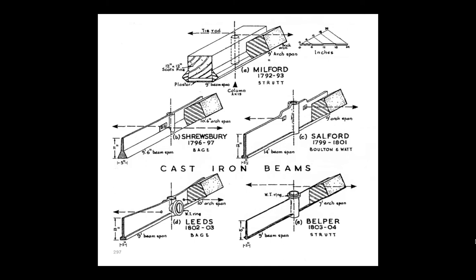Builders realize that all of these beams are much, much stronger than if the same cross-sectional area had been deployed in a simple rectangle. And today we know the reason for this, right? These are actually rudimentary flanges that are starting to give those beam shapes a much, much greater moment of inertia and much greater section modulus, because they're increasing the average distance of each little piece of steel from its neutral axis. As you put more and more material on the top and bottom, you're giving that beam a greater resisting moment arm to resist a load that's being put on it at its center.